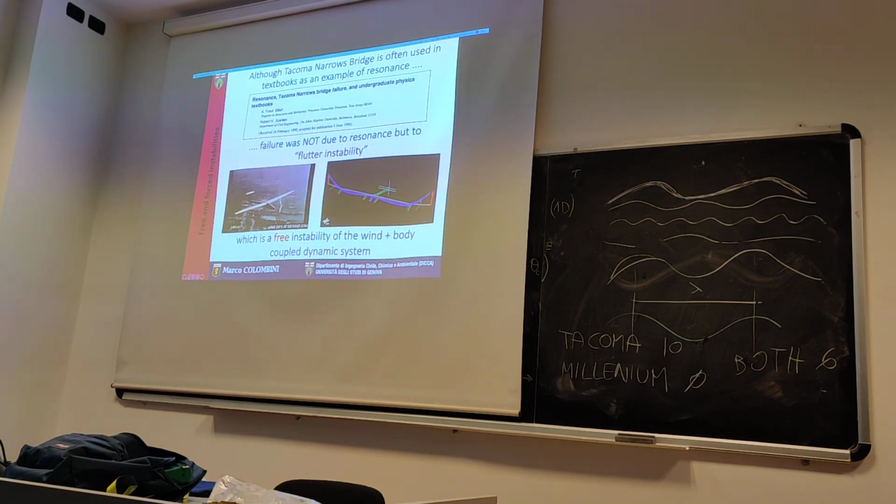Just the fact that the river is meandering creates bed forms on the inside and on the outside of the bends. And these are forced bed forms, because they are induced by the curvature, which is fixed. If you once again put together the sediment transport model and the flow in a meander, and you introduce some relationship between the flow and the bank so that the meander can evolve, that one is again a free system.